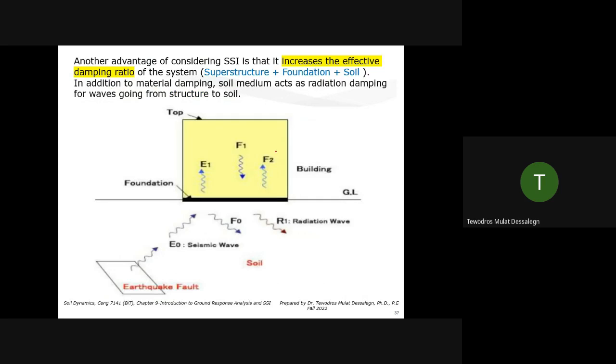Another advantage of considering SSI is that it increases the effective damping ratio of the system. If you're fixing the base, we're not considering damping, right? We are introducing high energy. Whatever input we apply on the structure goes into the structure and then reflects back. That's bad. There is nothing absorbing what's coming in.